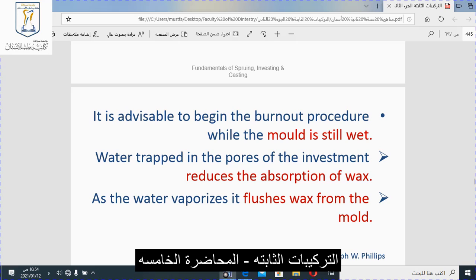When the wax burns and disintegrates, more carbide will be introduced into the material, so sometimes it will be brittle, as with base metal alloy or ceramic metal alloy. Sometimes the air cannot come out because the pores are filled with wax. So air is incorporated into the cast, giving back pressure porosity, or sometimes a rough cast.